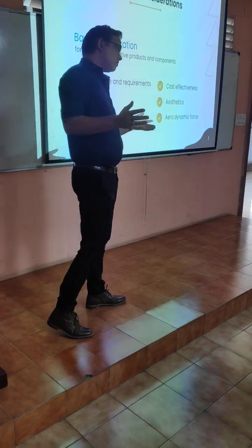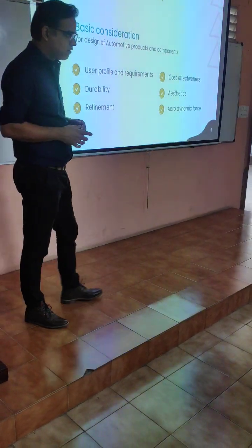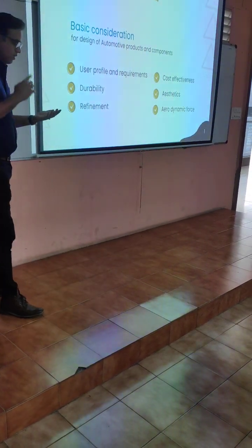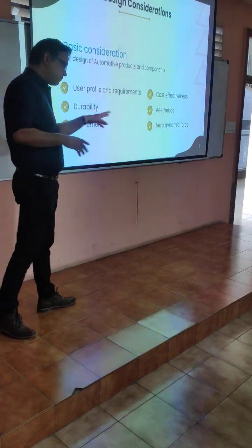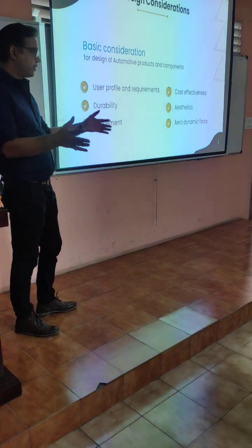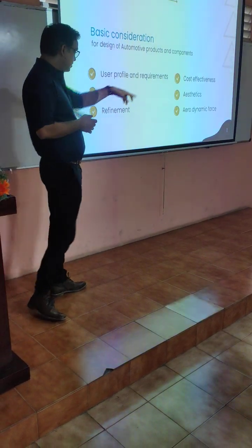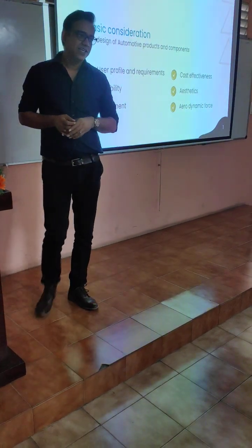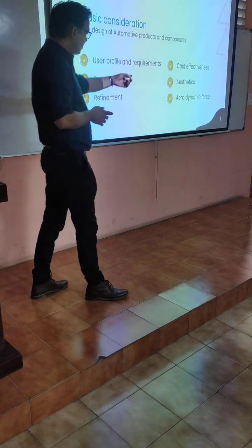Same weight, if you increase the speed to 100, that 5 becomes 50. It doesn't become 10. If you just do your power requirement calculation, simple calculation of speed and distance, right, you will get 8 for 100 kilometers. But when you do the full calculation, which includes this, then that will jump to 15. Because aerodynamic drag increases disproportionately, as in multiplication happens at higher speed.